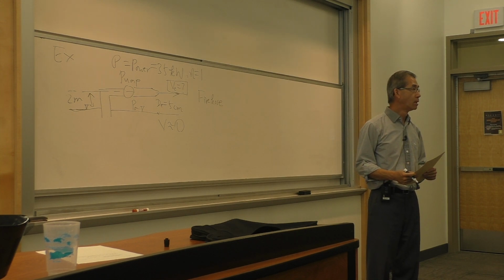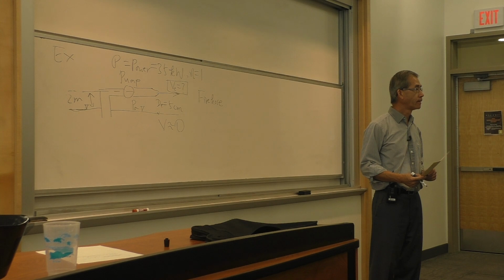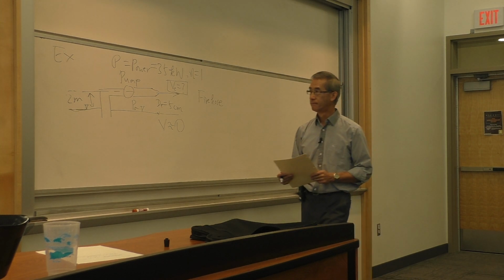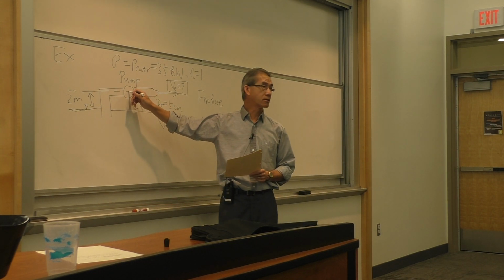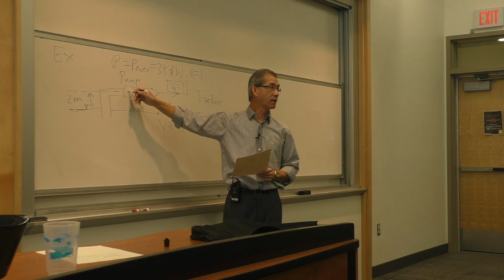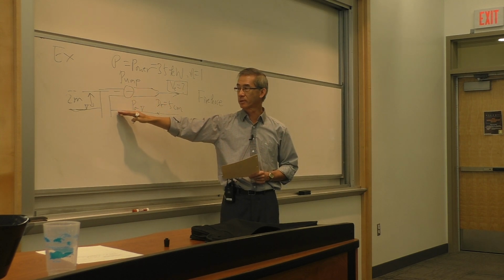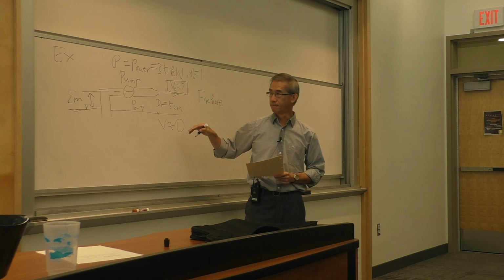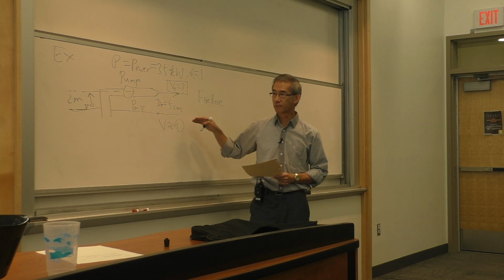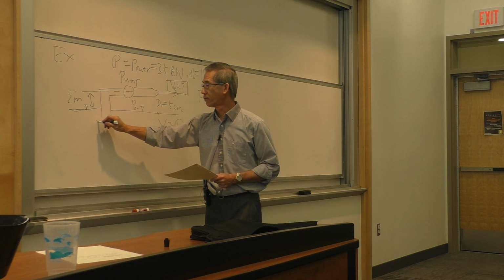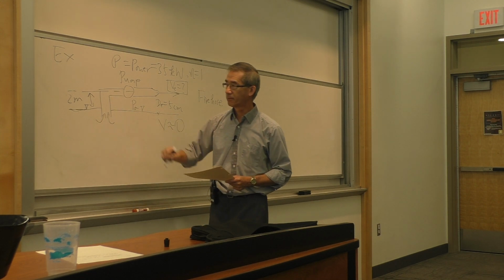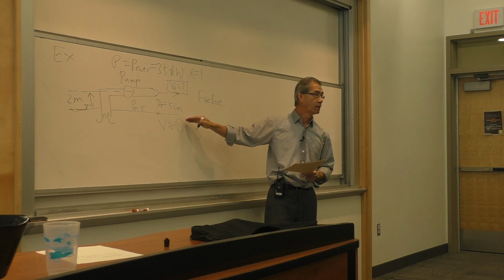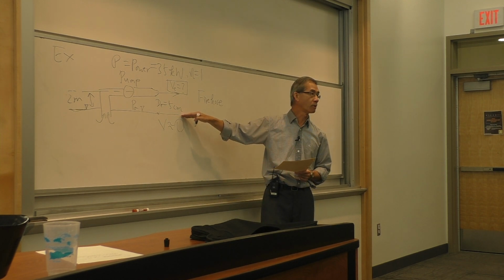Yes? Would the velocity be zero? Wouldn't we even know the size of the pump at the background level? Do you need to know the size of the pump at the higher level? No, but I'm only dealing with the water surface in here, where the water is being drawn in from this large reservoir. I'm not focusing on the immediate intake of the pump. I'm looking further away from that intake at this free surface of the water.